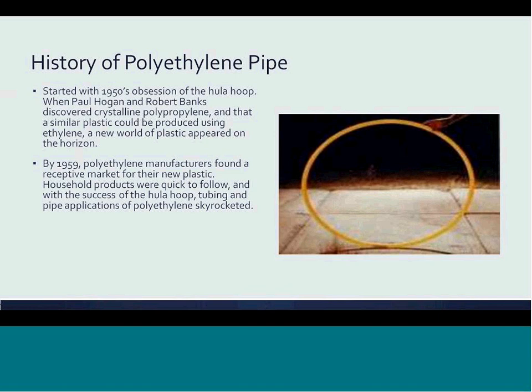The history of polyethylene pipe started with an obsession with the hula hoop. Well, I'm just going to take this as truth. Moderator Sean provided me with this slide. What I share with you is that the specification for piping materials for the ground loop has changed at least 3 times since 1948. There was trial and error resulting in failures in the past. The geo-pump industry learned from its early mistakes and has converged on this particular type of plastic pipe because it is fused, it has no mechanical fittings, and because it has great reliability when installed properly.